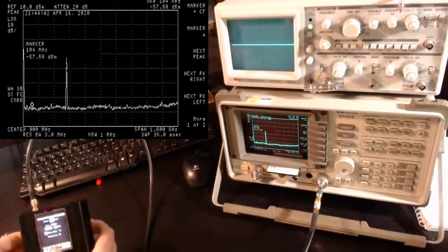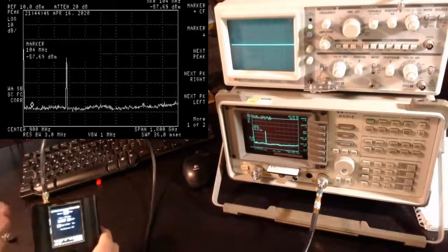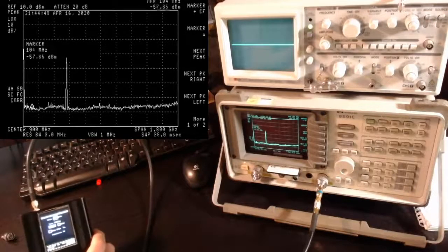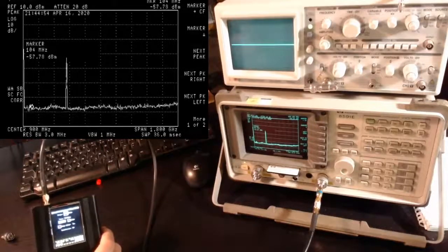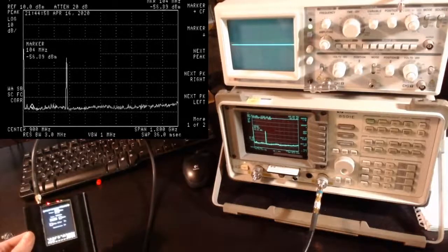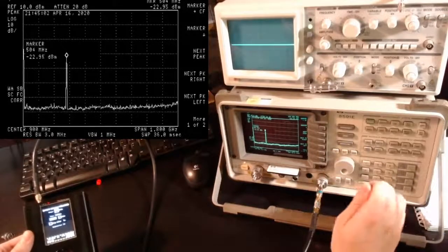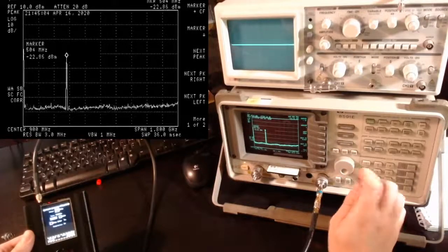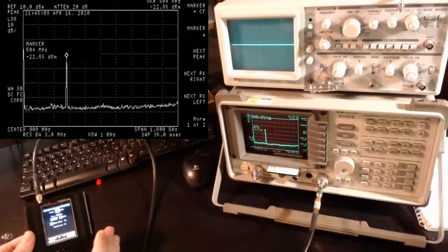Right. So we get this signal at 500 megahertz, and frankly it looks much better than what we observed in my previous experiment. So perhaps my sketch was not good enough, but here we are getting, so again, peak search, next peak, the main signal at 500 megahertz at minus 22 dBm. So in reality this is a 12 dBm, the gain currently is 26.